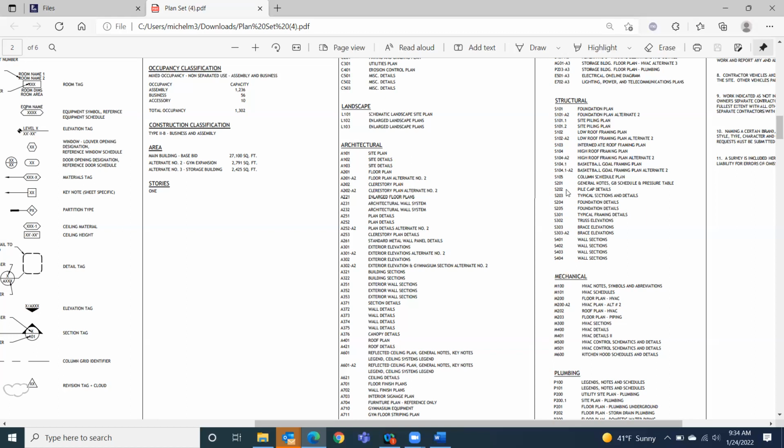All these are broken down into specific ways about how these sections work, such as in architectural drawings. Our A101 sheet is always going to be like our site plan. And then you'll see the A102s, your site plan details. Once we jump into the A201s, that's when you start working on floor plans, all different floor plans in the A200 section. In the A300 sections, that incorporates all of our elevations and goes from there. And we'll talk about that a little bit better.